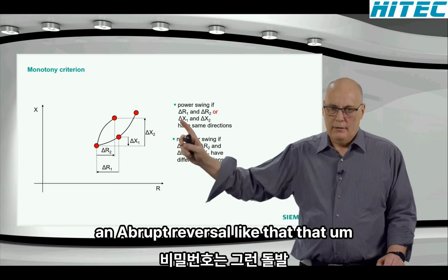When you come to the bottom, the movement slows down. So where it is interesting for the relay, the power swing impedance trajectory movement is fairly constant, fairly slow, but it must be continuous. It cannot jump. It cannot be slow and then all of a sudden have a rapid jump like that. That is not possible. That would be a reset. The jump of the trajectory would be a reset criteria for power swing blocking.